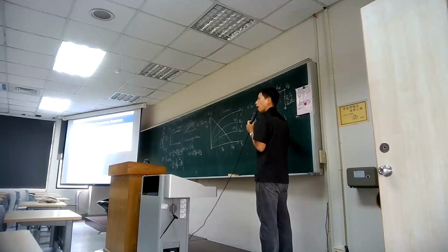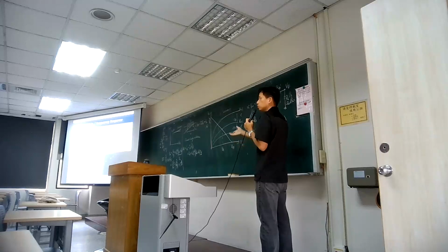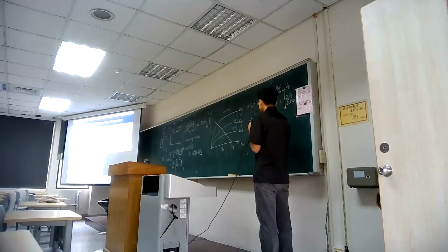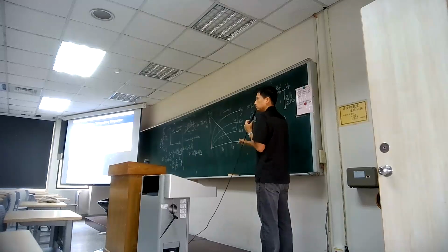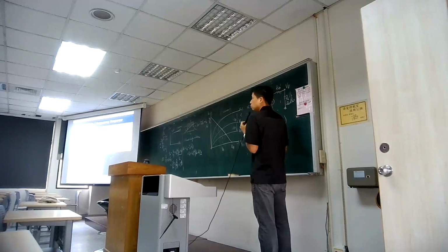That also explains why sometimes we see on a speaker, earplugs type speaker. What happened here is the load impedance is 5 ohm. So when you connect 5 ohm in parallel with a kilo ohm, it's mostly dominated by 5 ohm. So even though we get a gm of maybe 2 to 3 milliamp per volt, or even with a BJT, 40 milliamp per volt, you multiply with VGS, it seems the signal doesn't really amplify. The reason is because your resistance is too low.